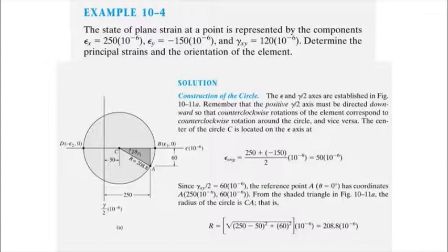Epsilon x is more to the right and epsilon y is to the left. So we make sure that our vertical axis, the axis for shear strain over 2, is towards the center, not exactly at the center of our graph paper, but close to the center, about 1/3 of the way.